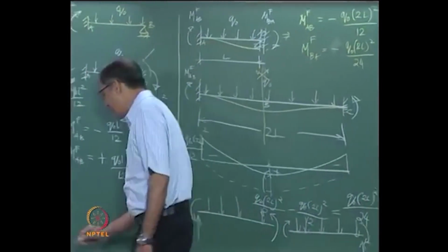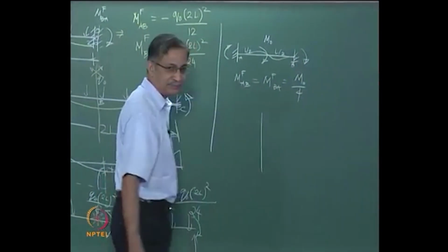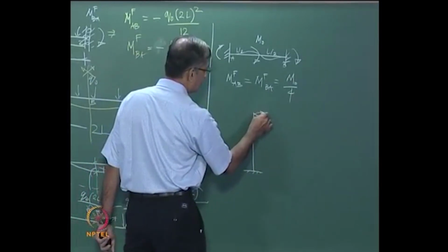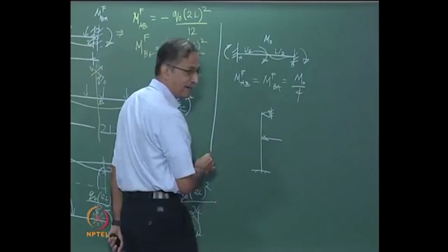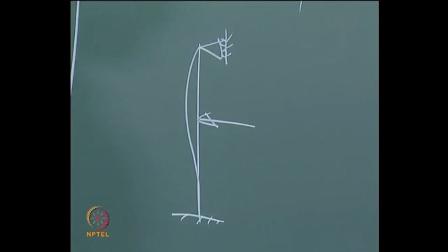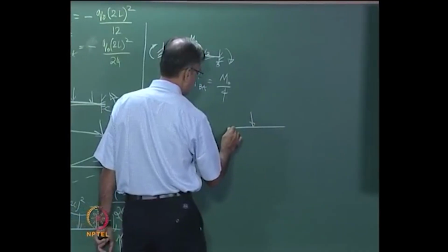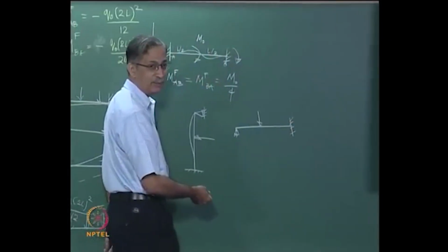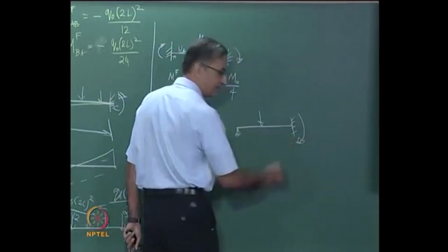Okay. So here you have a situation where that beam is vertical. You have a case like this, right? You have arrested this end, and this you propped, though it's shown like this. Where is your load acting? The load is acting here. What is the deflected shape? All this you should bear in mind. It's like this. So you can turn it over if you are more comfortable with this situation. Now you don't have any doubts. This is going to be always clockwise. Is it clear?